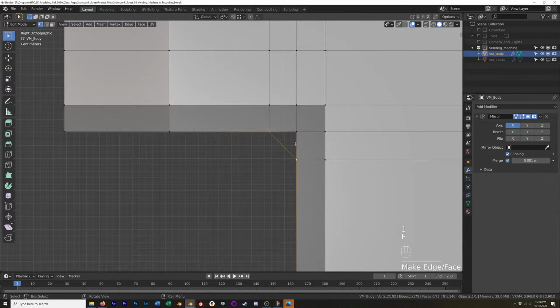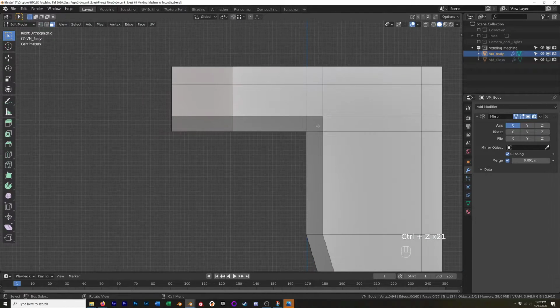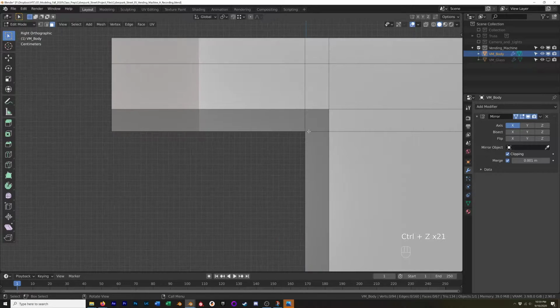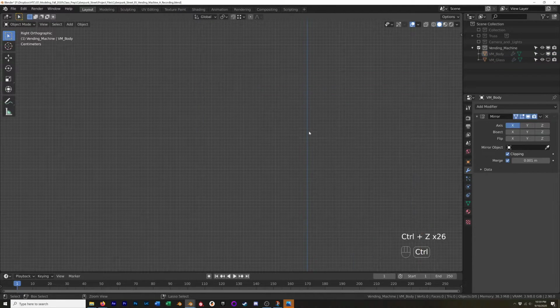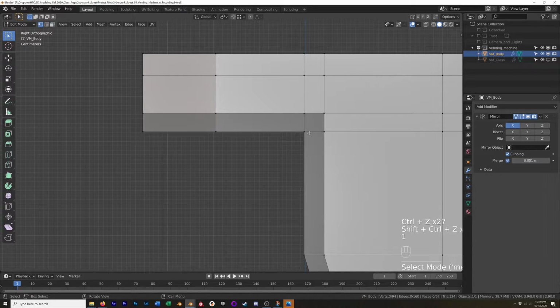Where you fill that in, and then you join those, and then use the knife tool to cut across. And then you merge vertices, but I just found a new way with the bevel, as I was telling you how I didn't like it. It just kind of clicked for me. So let's do it the easy way.